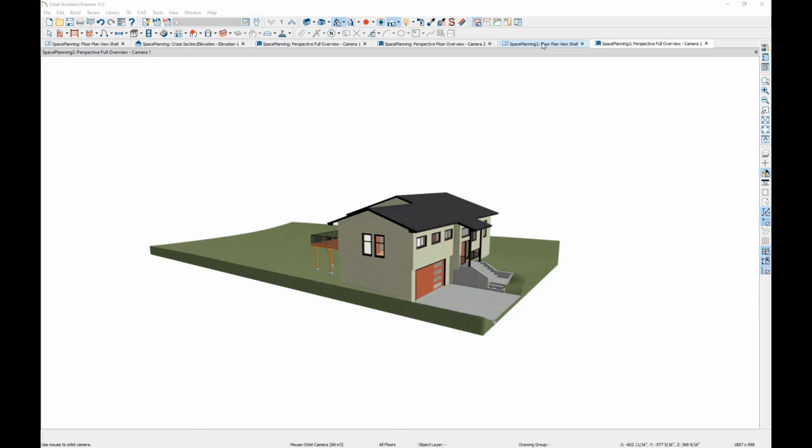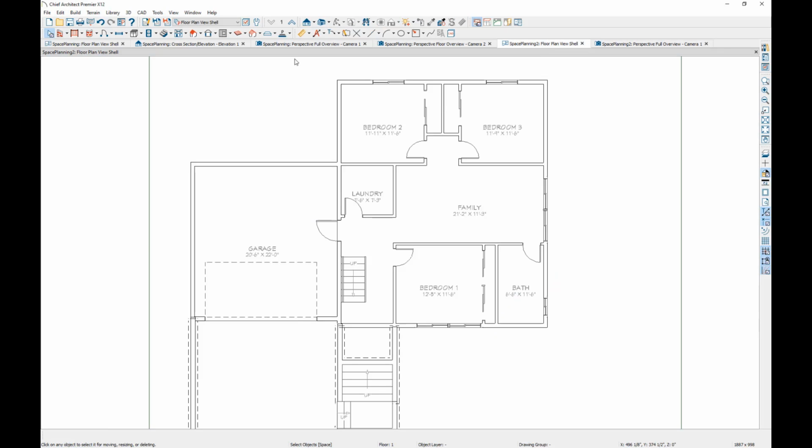So I'll come back to my project plan, and we're on level 1 right now. Even though most of this is probably considered a basement type of level, I did it all on floor 1, or we swapped it to floor 1, because I knew I would want some conditioned space on these walls, which is a little different than what I would have for my foundation. If I'm doing a basement type of scenario, often I'll make the basement level actually on floor 1.